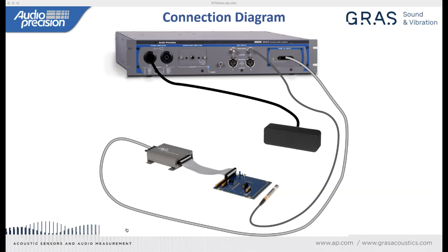And then just to address a couple other questions. Is there a single clock source for all 16 PDM channels, or are there multiple clock sources? It's a single clock source in the PDM16 that is electrically buffered to drive all the microphones.